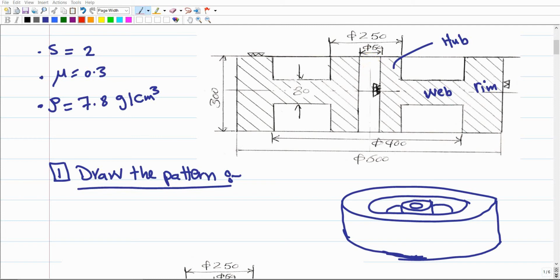Usually for this kind of product, we form these holes by casting directly, and we don't machine them using the drilling process, especially since this length is kind of long, somehow 300 millimeters, too long to use a twist drill to open this hole. So it is advised to form or open this hole by the sand casting process, and this is what we are going to do.